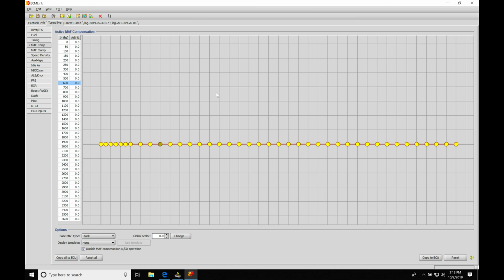Now the long-term fuel trim is going to be constantly monitoring the short-term fuel trim. And as we drive around, it's going to be populating learned data. So if the short-term trim is constantly taking out, let's say 5%, the long-term trim will absorb that and then turn the short-term trim back to 0. So the short term is going to be the instantaneous correction. The long term is going to be more of a long-term version of what the short term is doing.